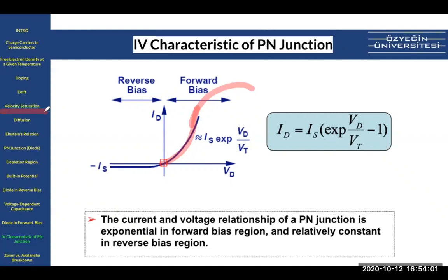All the electrons and holes at some point will be subject to a kind of saturation because of the recombinations. Basically, when they start to move so fast, the electrons start to hit, and when they hit, they cannot gain their speed back. That is the mechanism that causes saturation.